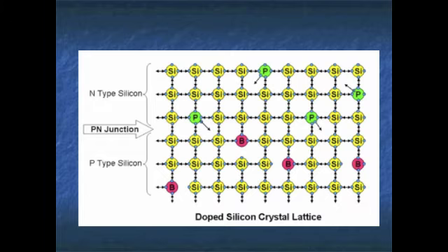In this picture, the top half of the crystal has phosphorus impurities in it. The phosphorus dopant makes the top half N-type silicon. Note the 4 free electrons. In the bottom half, the crystal has been doped with boron, making the crystal p-type.